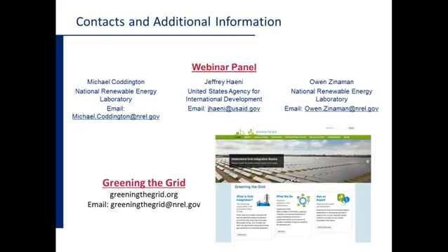One other thing I'd mention is that over the last handful of years, we've seen a significant move toward these microinverters, where you've got a PV panel or a module on a rooftop or maybe ground mount, and each one of these modules would have a microinverter, a small inverter that changes the DC power to AC, compatible with the grid. And what's nice about those systems, if one of them fails for whatever reason, the other parts of the system continue operating, giving a higher reliability.